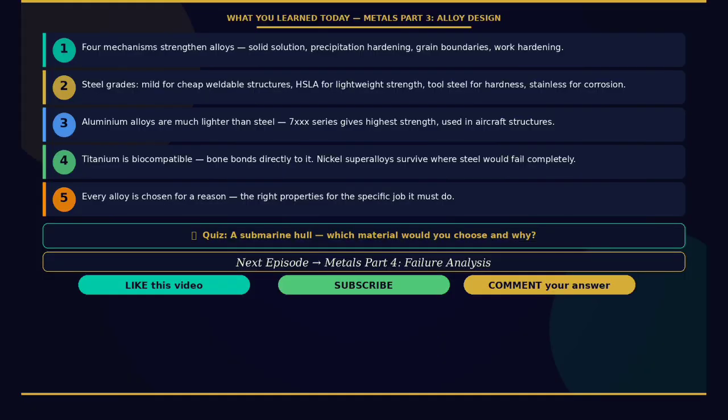Let us bring everything together. 4 mechanisms strengthen alloys: solid solution, precipitation hardening, grain boundaries, and work hardening. Steel exists in thousands of grades, each chosen for specific properties. Aluminium alloys are much lighter than steel. The 7000 series gives the highest strength for aerospace. Titanium is biocompatible. Bone bonds to it directly. Nickel superalloys operate where steel cannot survive. Every alloy is chosen for a specific reason.